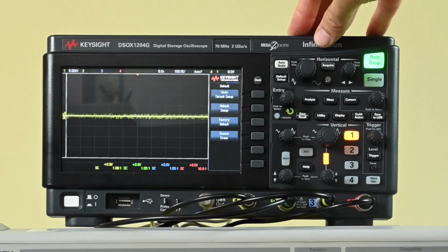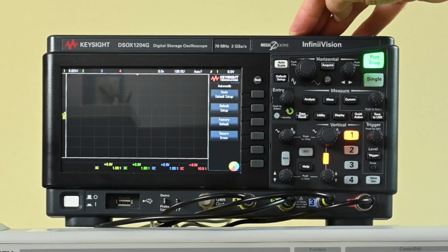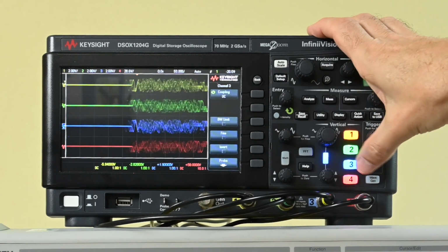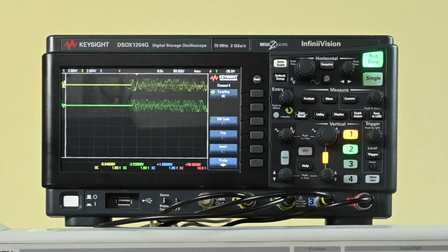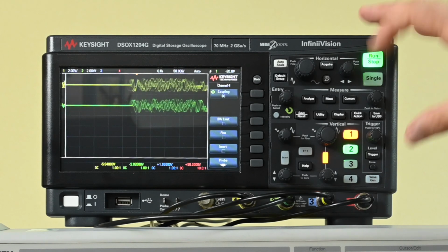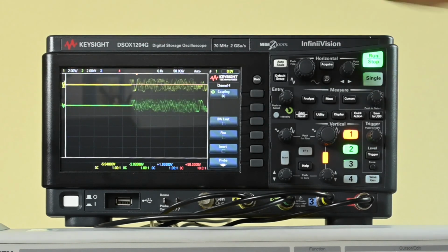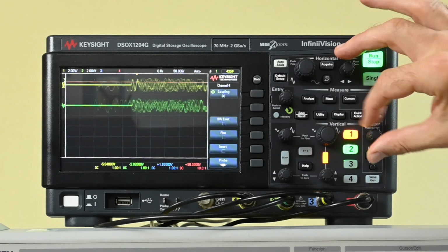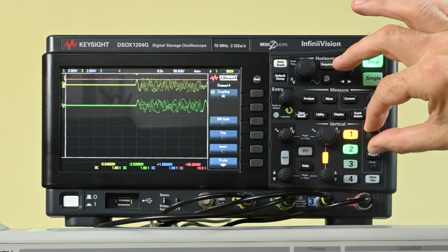Let's try to see if we can get a little bit better signal out of that. I'm going to use auto scale to see if the scope can make any sense of that. Let me just disable 2 channels here. And I do get to see already something that looks like a burst, and that makes total sense because GSM sends its signals in bursts. It's not triggering perfectly yet. We're triggering on channel 1. I can see that right here. So I'm going to go to the highest peak here. Yeah, I think I'm getting a little bit better triggering.